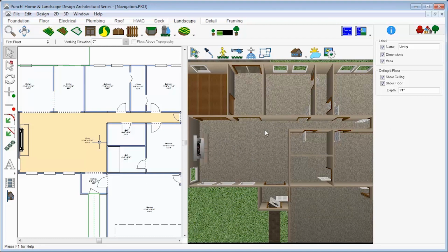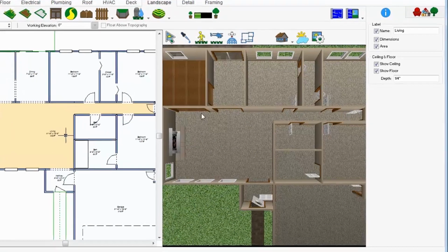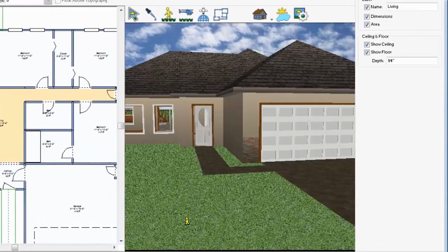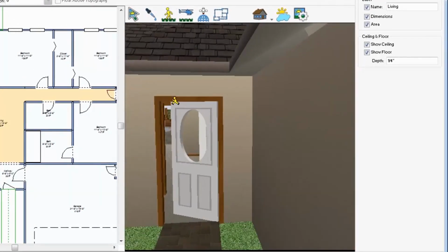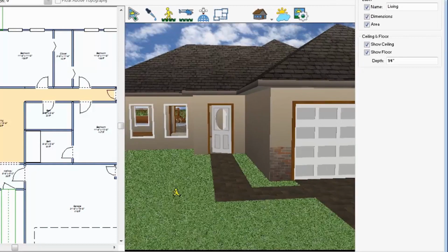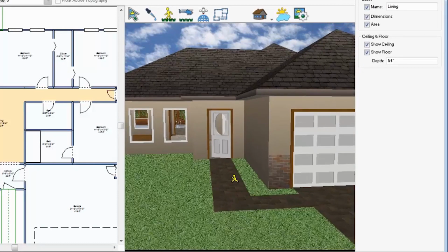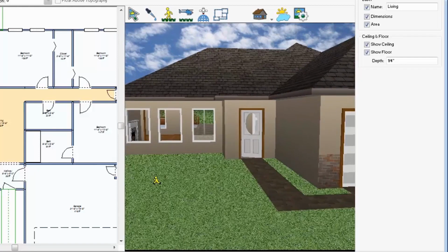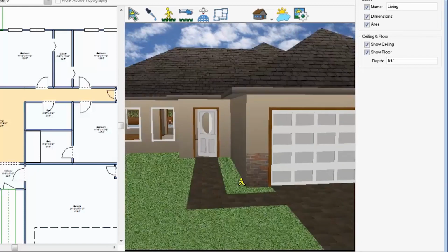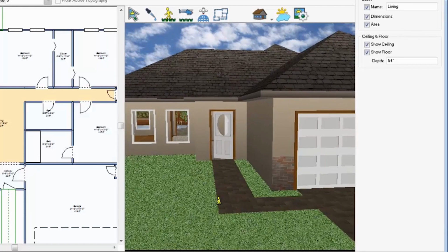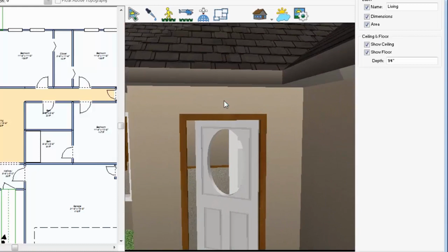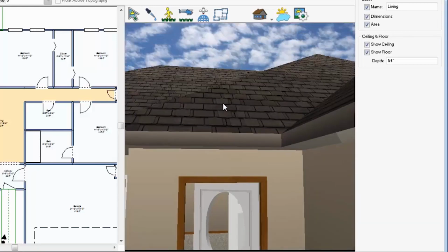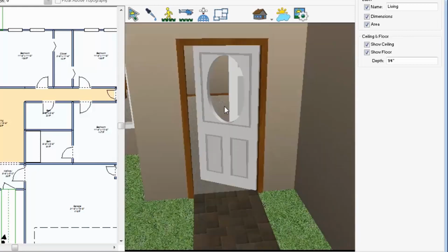full 3D view. Click the Animated Walkthrough tool, press the left mouse button, move it forward to move closer, back to move away. Press the right mouse button and do the same to move up and down, or pan left to right. As you move closer, you can use the wheel on your mouse and scroll it to stand there, but look up and down.